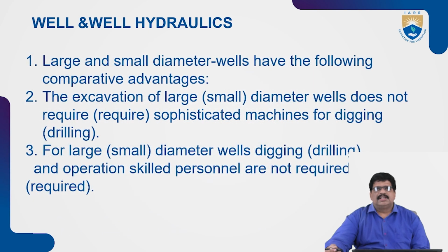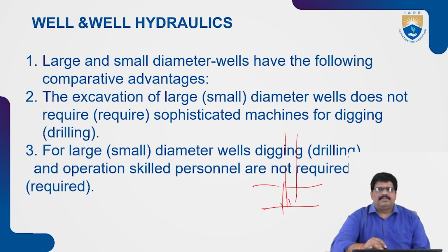Next, large and small diameter wells. Let us see the behavior of the large and small diameters. The comparison of advantages: for excavation, the small diameter well does not require sophisticated drilling machines, which put drilling machines inside the layers, as we saw previously. For large diameter digging, operationally skilled personnel are not required.